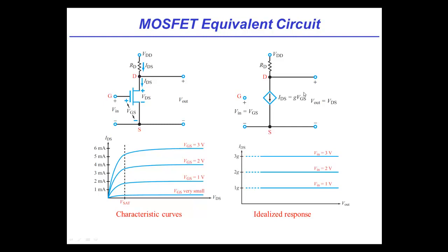So I see. What you've done is set it up by ensuring that I live in the right side of the curve, where I told you earlier that there's no drain voltage dependence. I now basically get an equation for the current that is completely independent of VDS. That's right. That's what we've done. Of course, we're assuming that the person who designed this has either given us an input that will keep it biased at a high VDS, or we're going to play some tricks in an intermediate or advanced class so that VDS always stays where you want it to be.